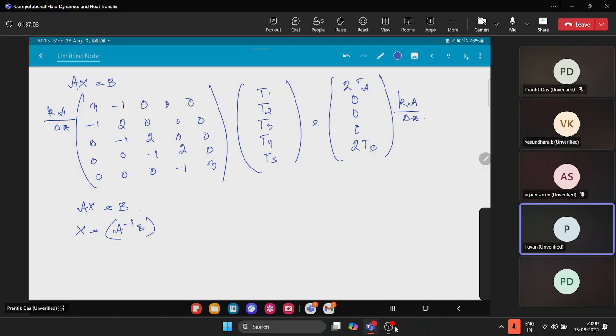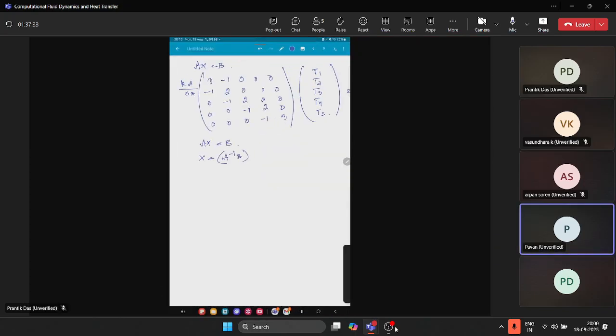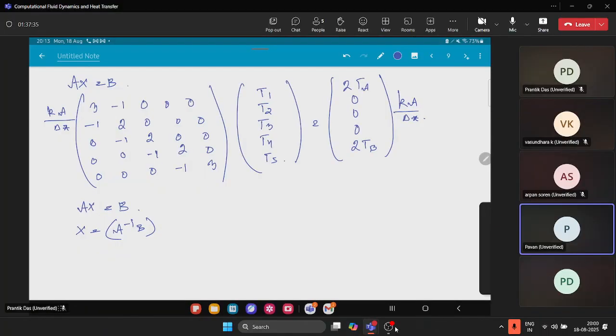Sir, I have a doubt regarding the Navier-Stokes equation, the starting equation that you wrote. I have a statement, just say whether I am right or not. If we consider phi as a vector field, there is a nonlinear term, rho into V into V. One V will be related to the field itself, and another V will be related to the fluid particle, right?